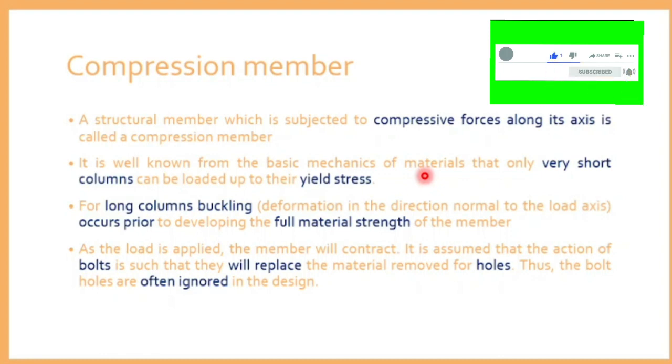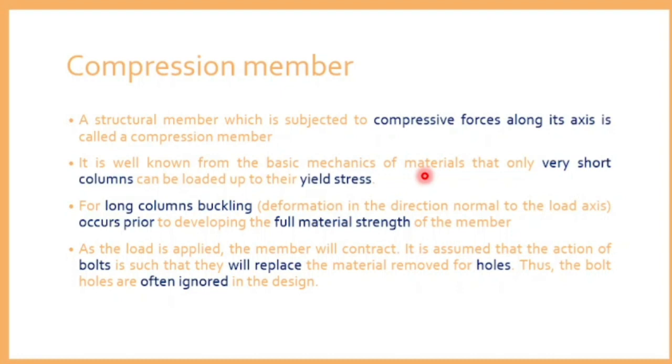UTM, and you are testing mild steel, how are you conducting the test? You are stretching the material and finding the yield strength. Yes or no? If the yield strength is 400 or 410, you find it by stretching the material and finding the yield stress. Is the load acting the same way in the columns? Do you have any tensile force here? No, the column carries compression force.